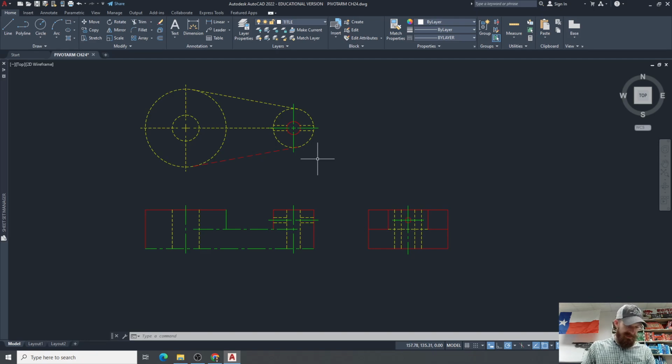All right, let's talk about change. Change. What is the change tool? The change tool is an old command that allows you to change properties in command line format, right? You can change points, such as the endpoint of a line, or you can change properties. So if I type in change, and then let's say I select an object here, right? Ta-da! I can change like an endpoint, right? I can take and form a new endpoint if I wanted to.